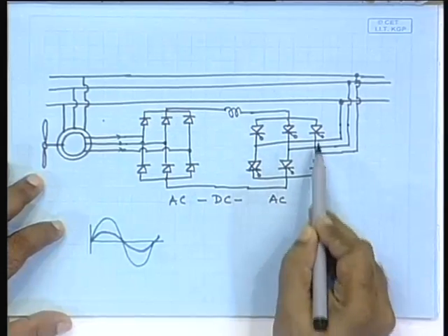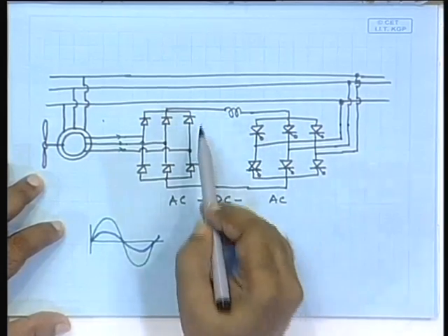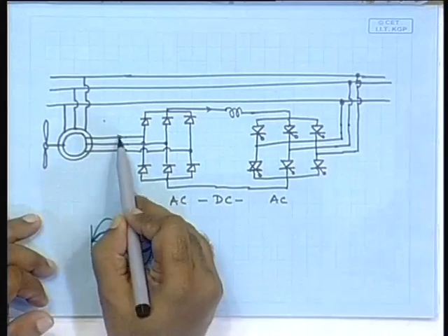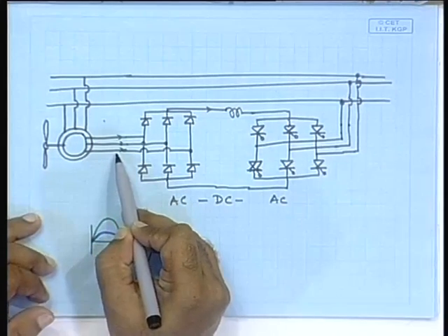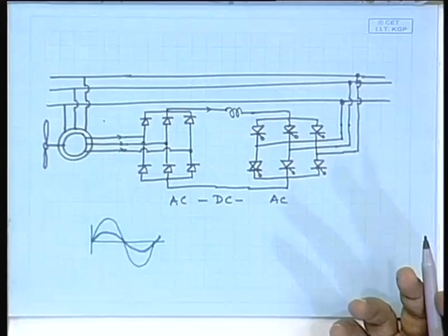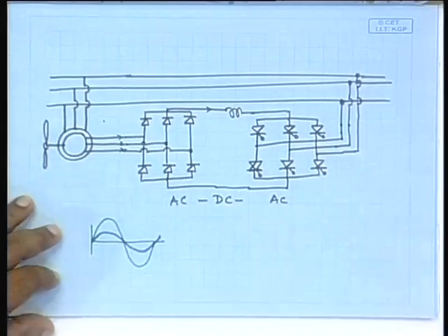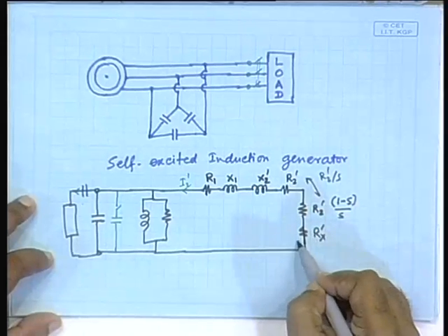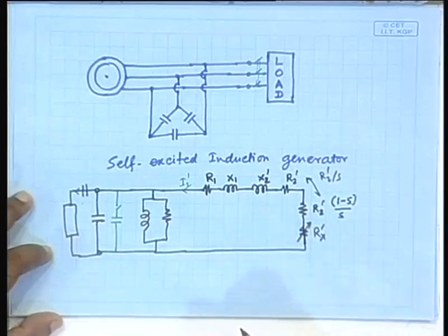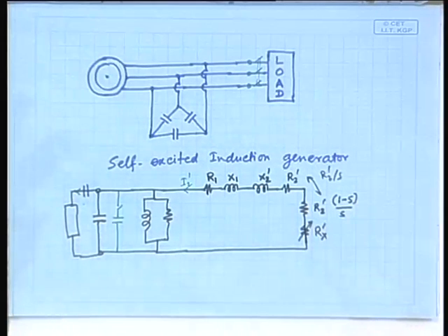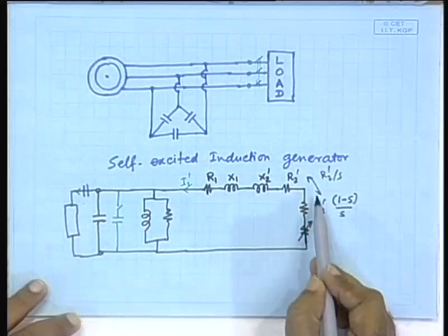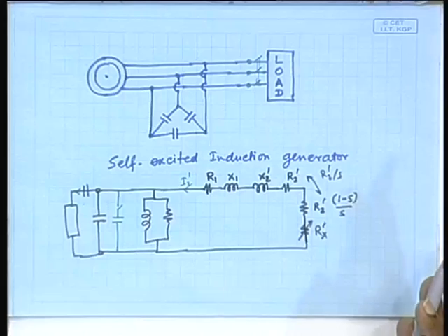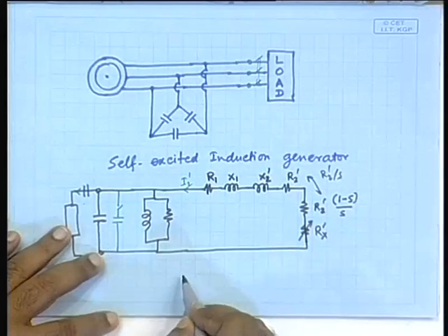Okay. So, by controlling these firings, it is possible to vary the amount of current that flows here, and to vary the amount of current that comes from here, and therefore the resistance seen by that. So, effectively what will happen is that this resistance will vary, it will be a variable resistance, and the control strategy will be to keep the total resistance here constant.